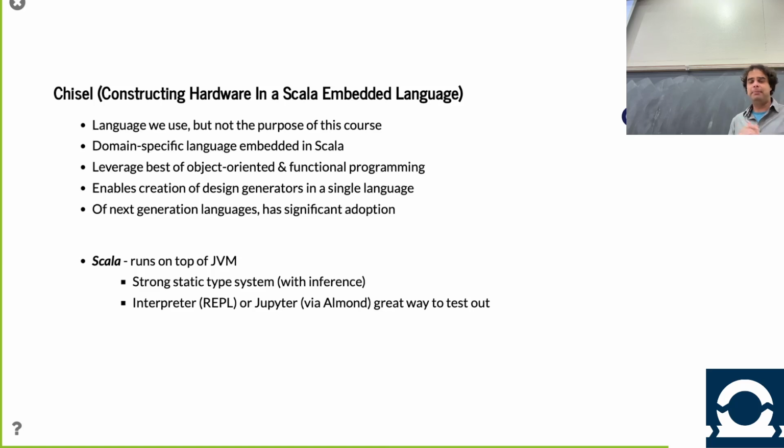And what is Chisel able to do? Well, it's able to take the best of software-oriented programming, such as object-oriented and functional, and bring those to hardware. It also makes it easy to make generators, where that generator idea I was pitching is a really strong idea. It's actually already widely deployed in industry with Verilog. And the question is, wait, how do you do it with Verilog? Verilog is so restrictive. And the answer is they use a two-language approach, right? They have, whether it be Python, Java, Perl, or even Tcl, stitching together Verilog strings to generate the component they want. That works for things like a crossbar, where you can imagine how to write those for loops to generate the strings of text you want to be the right Verilog. People do this. It's widely done in industry.